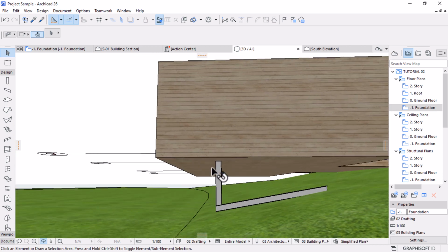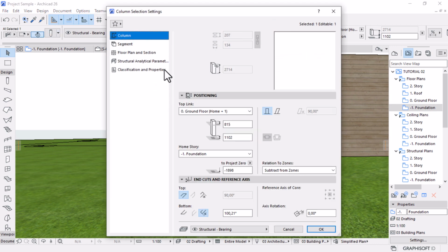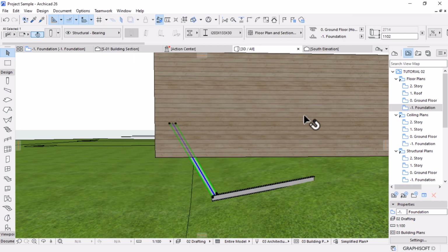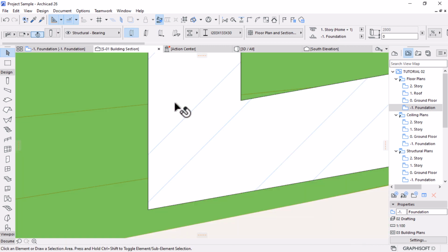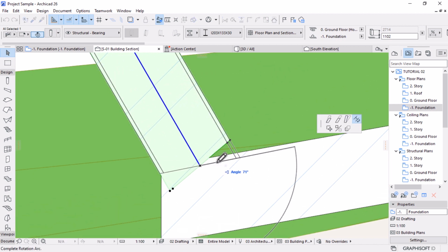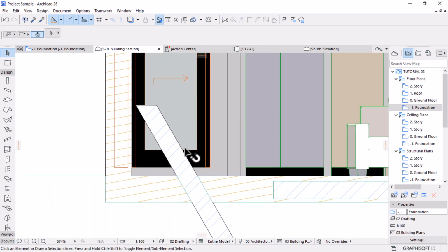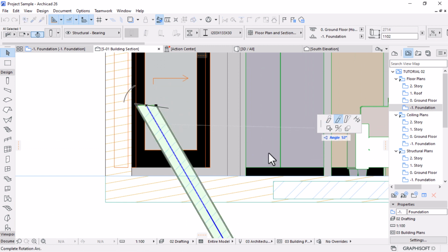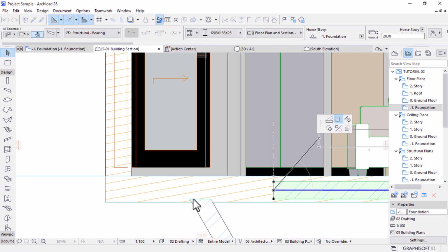It looks great. And then this has to slope a bit. Let's open its settings under column, make it slope a bit by maybe 60. Yeah, something like that. Okay, so we need to fix the joint between this. Let's fix the joint. Yeah, something like that. All right, and then it has to connect with the, I'm gonna stretch it from here to this, because it has to connect with this beam here. Stretch this beam all the way to there.